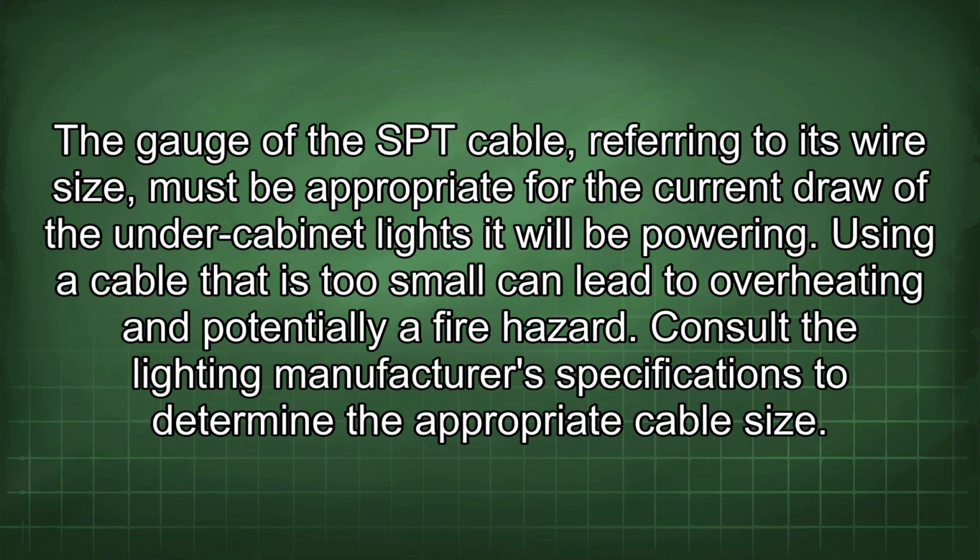The gauge of the SPT cable, referring to its wire size, must be appropriate for the current draw of the under-cabinet lights it will be powering. Using a cable that is too small can lead to overheating and potentially a fire hazard. Consult the lighting manufacturer's specifications to determine the appropriate cable size.